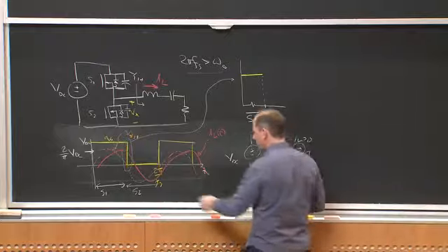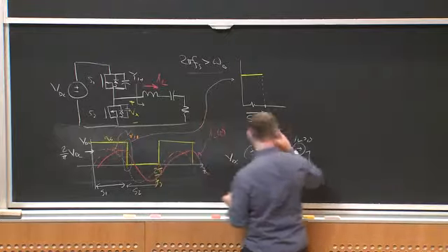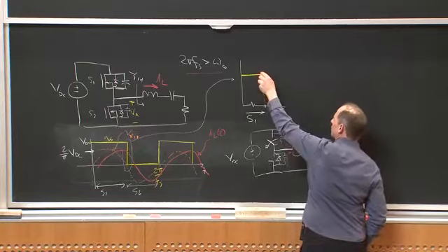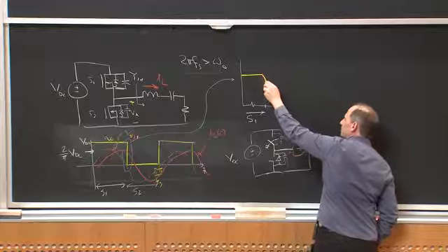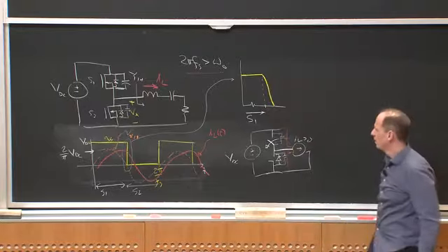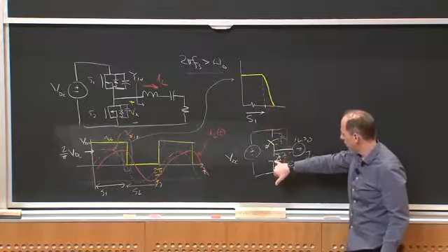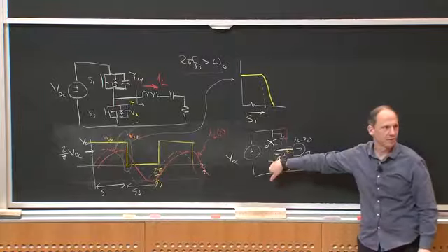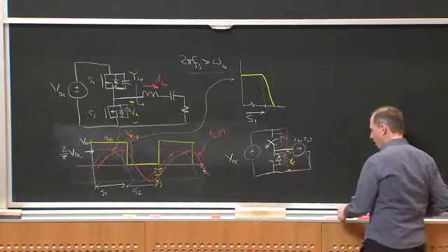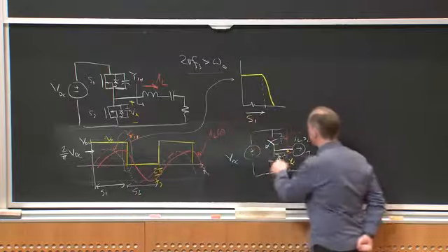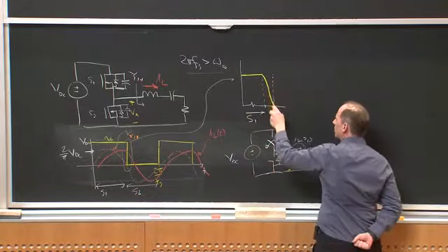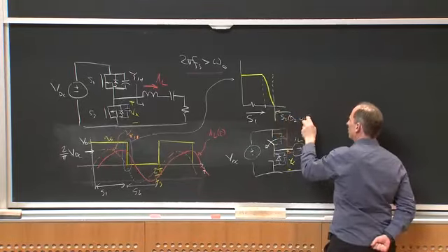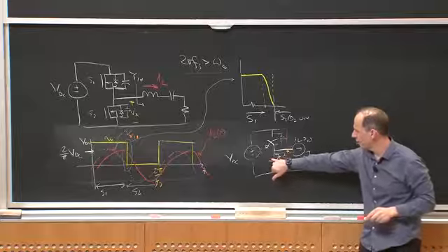So then if I were to look at this voltage, I'm going to zoom in right at this time period when I have both S1 and S2 off. What I'm going to see is a transition that's going to do something like this, okay? And then when this voltage hits 0, and this is voltage Vx, the diode's got to turn on, right? So if this was S1 on, even if I don't turn this bottom switch on yet, when this hits 0, I'm going to get S2/D2 on. The diode will turn on naturally, and then I can turn on this switch with 0 voltage.